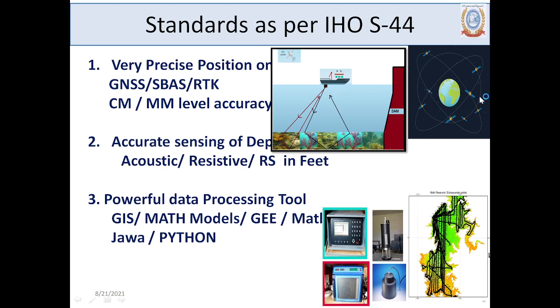So now this is a GPS satellite system. Similarly, you have GLONASS from Russia, then you have Chinese satellites, French satellites, and many satellites. India also has its satellite but not available for commercial use. So with this many satellites, say for example at a time you will have access to see more than 30 to 40 satellites. But mathematically, you need a minimum of 3 to 4 satellites to get your position accurately fixed. So all other satellites are just for cross checking, cross verification, or if one data is not of quality, you can always cross check with others.